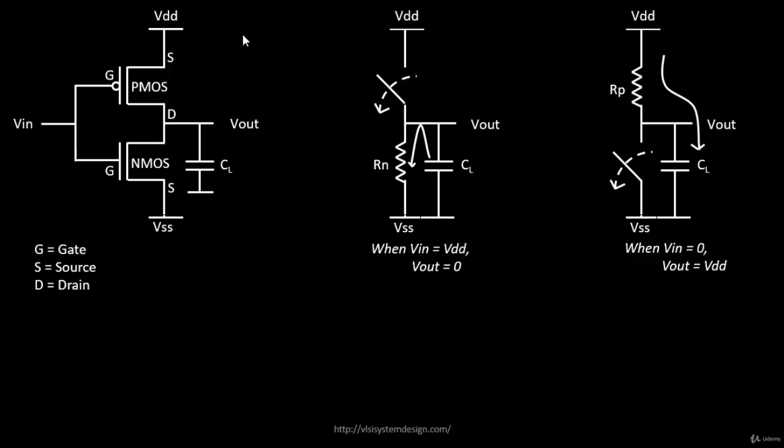In case of a PMOS, the source is connected to VDD. In case of an NMOS, the source is connected to ground, because of the potentials and the way the electrons or the holes behave in case of NMOS and PMOS respectively. So that's the reason. From this observation we also need to add some more naming conventions.